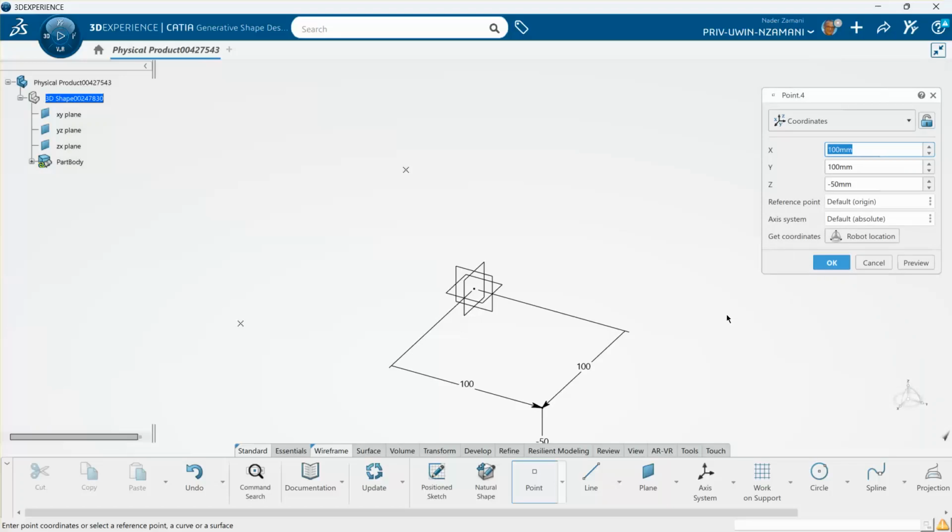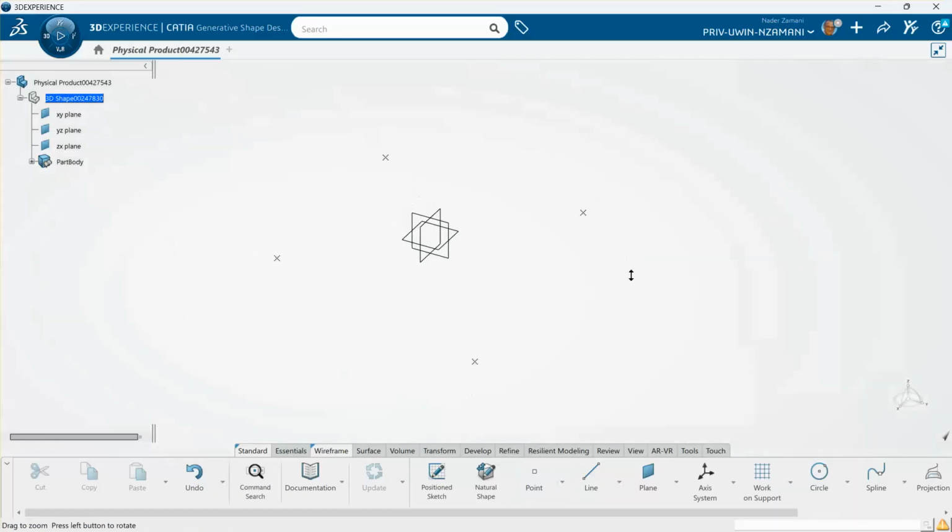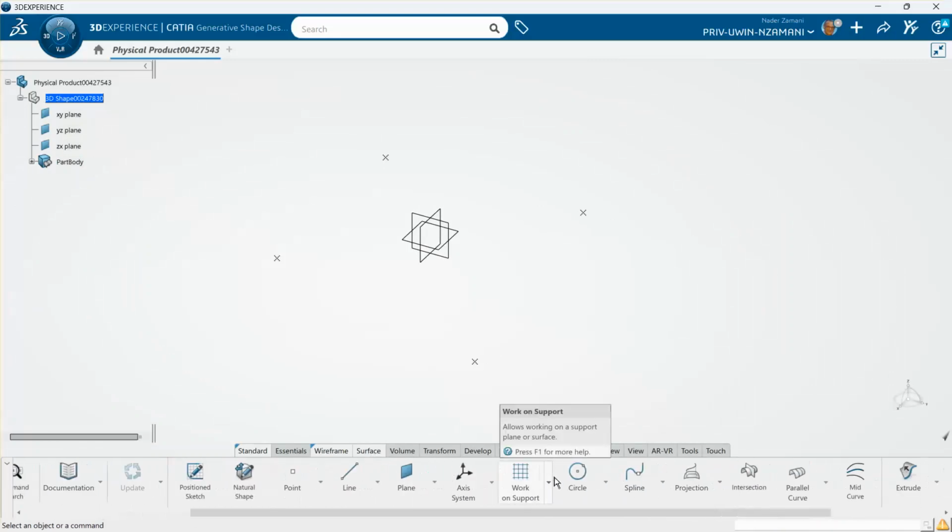This is to make it go below the horizon. Okay. And finally, minus 100 for X, 100 for Y, and 0 for Z. We say okay and cancel. So basically we have 4 points here, and these 4 points do not lie on the same plane. Therefore, when I put a surface on it, I go to the surface tab, and there is a fill, F-I-L-L option.